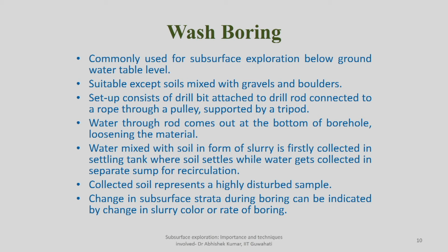But whatever slurry you are getting here, it is possibly indicating what kind of soil is there. In order to understand if there is a change in strata, soil type and soil stiffness, you can observe the slurry. If you get slurry of one color and suddenly you start getting slurry of a different color, that means at that particular depth of the borehole you are encountering a change in strata. Earlier you were getting some clay soil, now you are getting sandy soil, or maybe soil mixed with some organic material, or dark material, light kind of visual inspection.